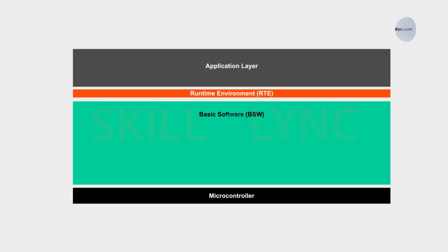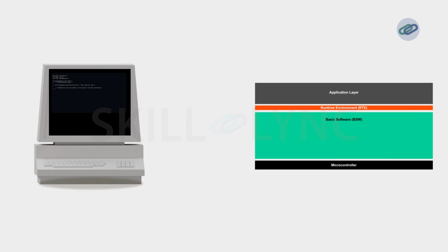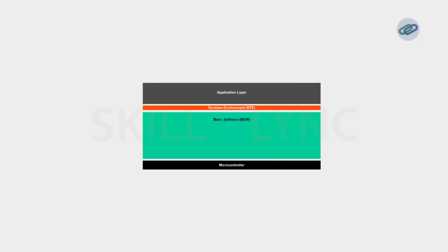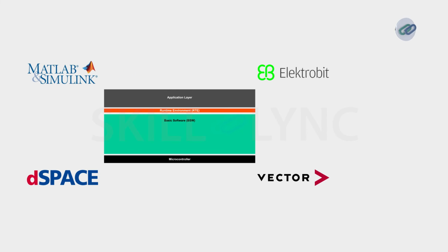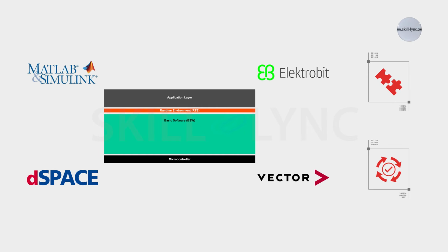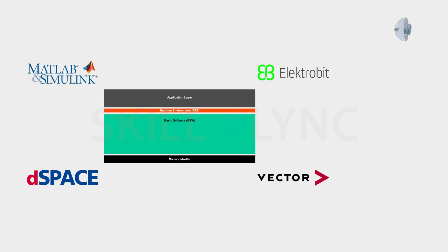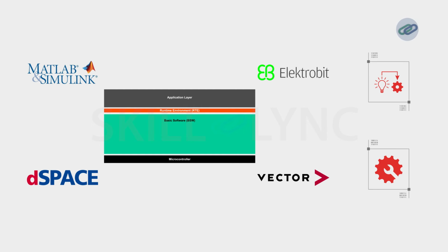Classic AutoSAR benefited from the development of a more robust tooling environment. This functions to streamline the software development process and enhance developer productivity. Commonly used tools and software platforms for classic AutoSAR development include Elektrobit, EB tresos Studio, Vector DaVinci Configurator, dSPACE SystemDesk, and MathWorks tools for AutoSAR. This ecosystem ensures compatibility and consistency throughout the development cycle, from the time of requirements specification to implementation and testing.